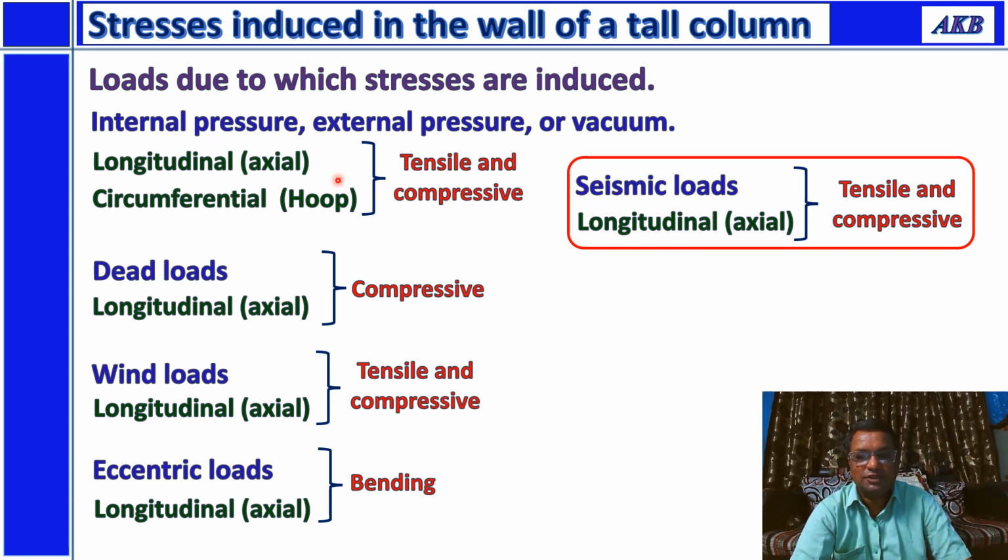In my earlier discussions I have covered all this: stresses due to internal pressure, external pressure, or vacuum, then stresses due to dead loads, stresses due to wind loads, stresses due to eccentric loads. I have covered all this. Today I'll be talking about stresses that are induced due to seismic loads. So let us understand how to deal with this.